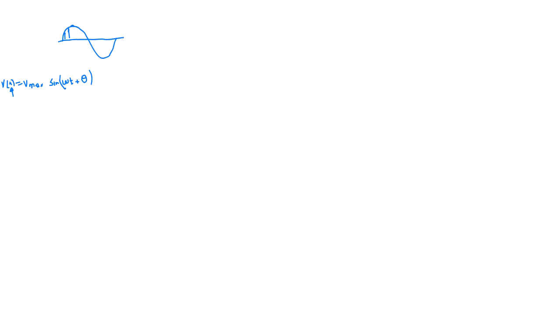If there is no phase shift for our case, this one will be 0 degrees, and your sine wave will be Vmax sine omega t, 2 pi f t. So this omega will be fixed all the time, 2 pi 50 hertz.